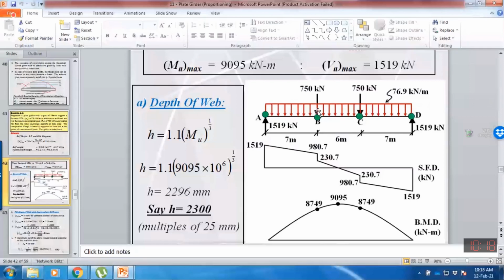So it means that from the top at points B and C, there are chances that the web may cripple or local crushing may occur due to the heavy force. Similarly, due to the heavy reaction acting at the bottom, the web at the bottom flange may crush, cripple, or buckle.